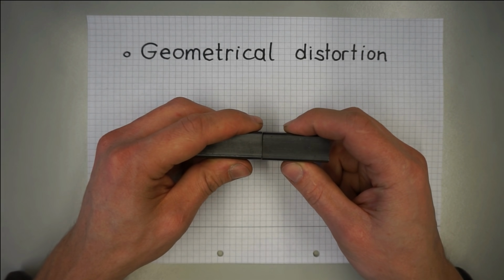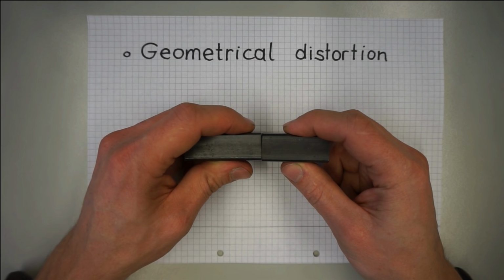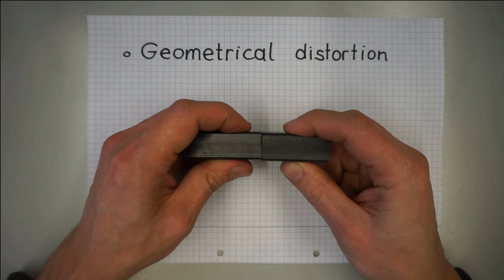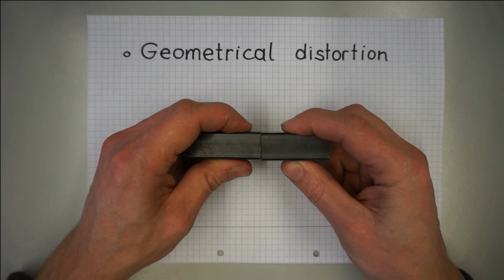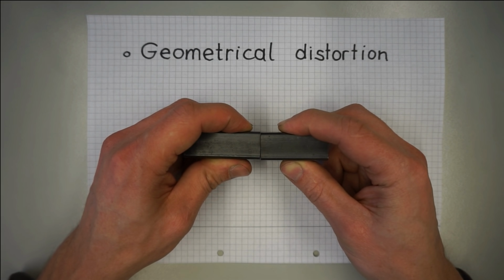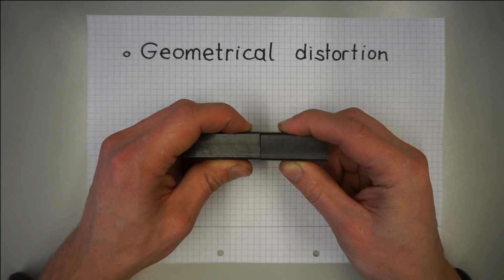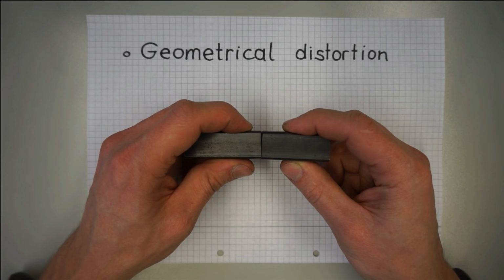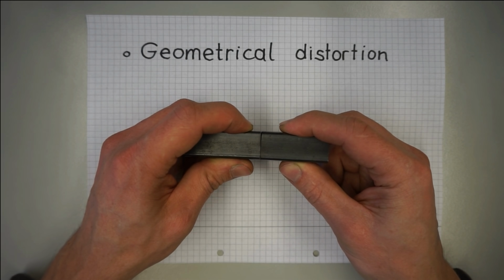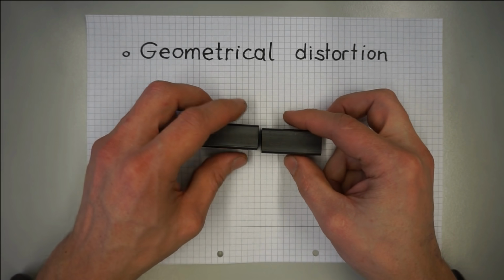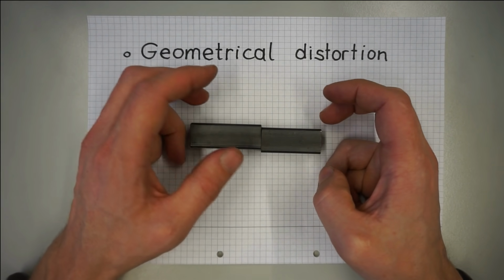And what happens when we tack with a gap is that, if we tack here, the gap closes a little because the cooling tack contracts, depending on the case, more or less freely. The master anticipates that and positions the precut so that after the tack has contracted, the workpiece geometry is as desired. Of course, that's an eyeballing task, and more commonly welders mechanically clamp or straighten the assembly until tacking has progressed sufficiently.